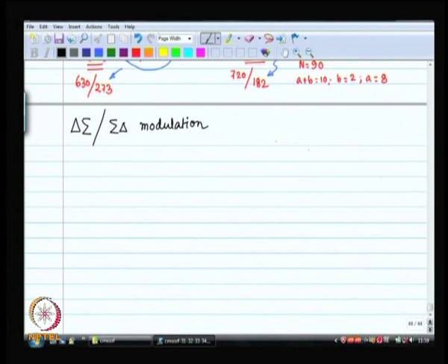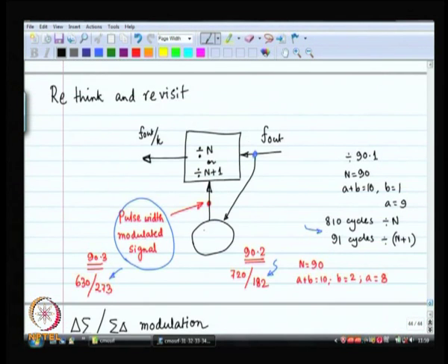So, the thought is that you want to randomize this pulse width modulated signal over here. You do not want it to be so deterministic, you want to create some randomness over there and you want to break the period at the output. You do not want the period of 1 megahertz. The period happens to be exactly equal to the channel raster, right, frequency. That is not good, that is exactly what you want to break.